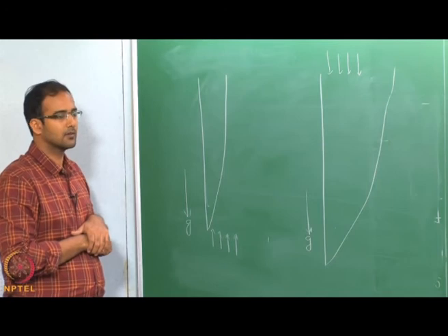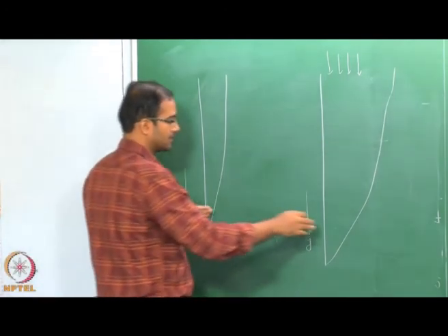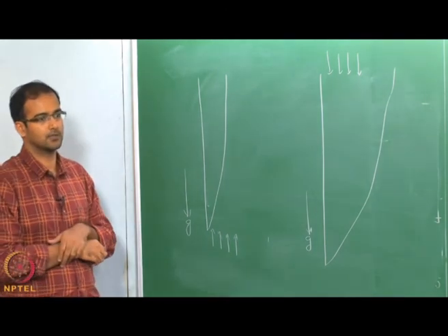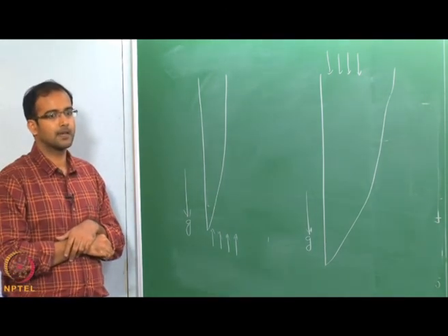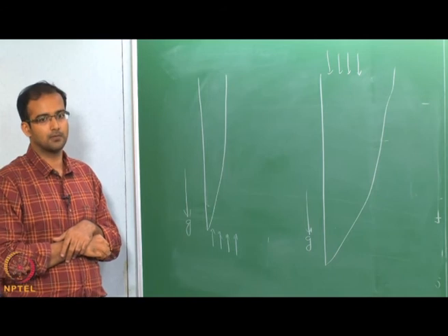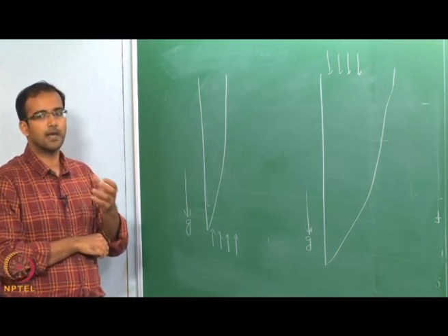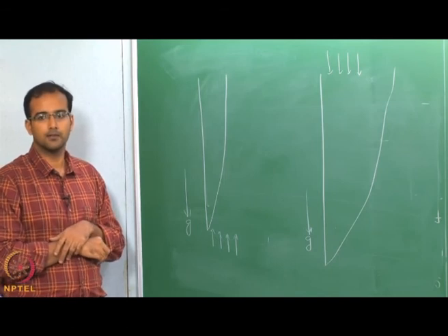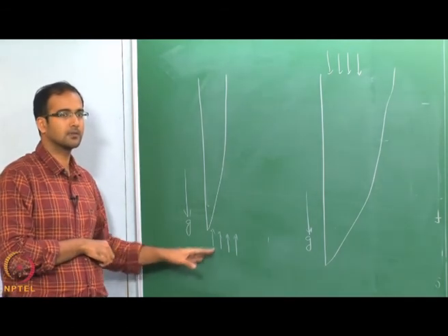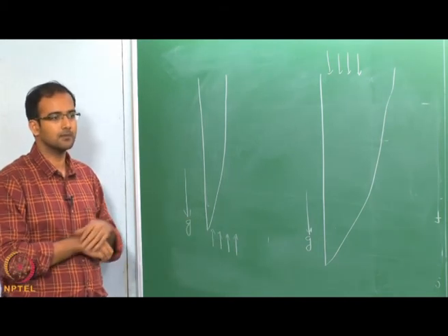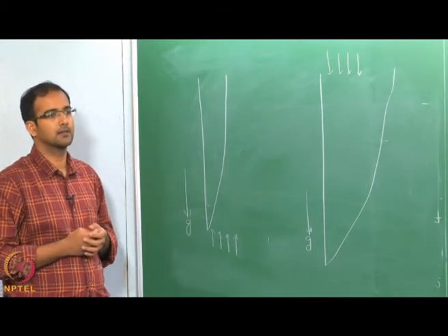Okay. So when we do these kinds of flows, what is the way to calculate the similarity solution? Is there a similarity solution for this problem? Well, the thing is, what is the correct similarity variable to use, because when you talk about forced convection boundary layer, we use the Blasius variable, but natural convection involves the Grashof number.